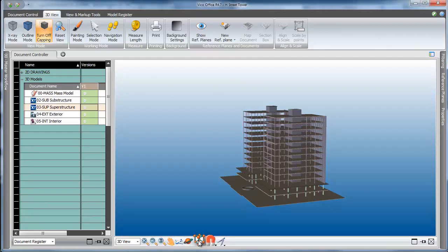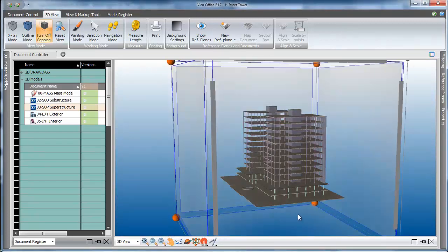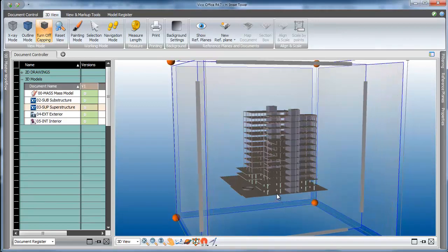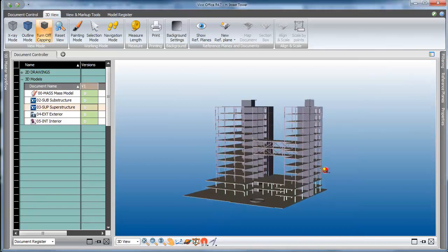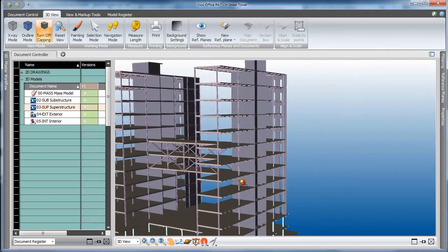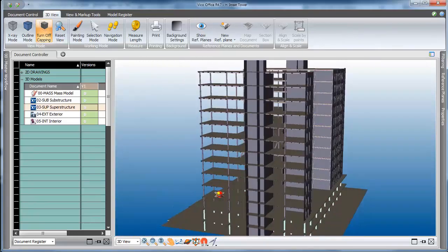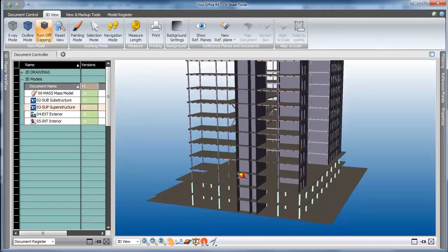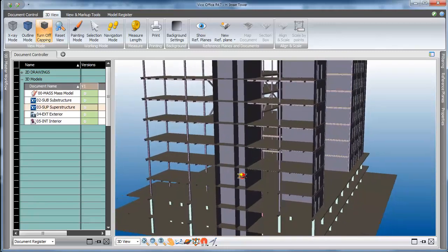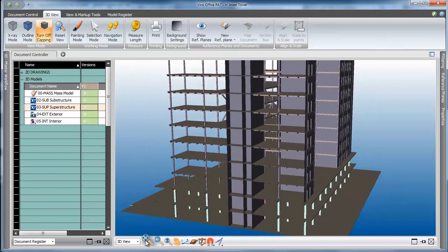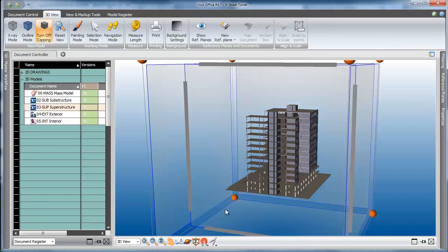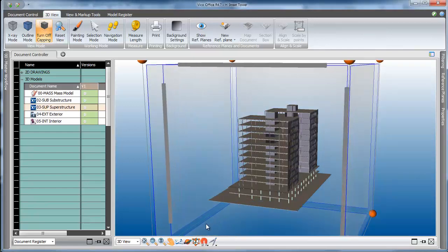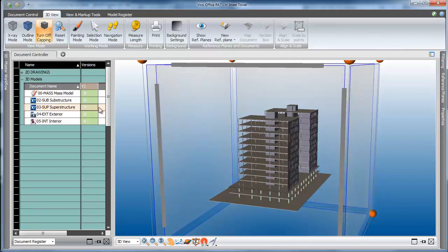If you ever want to get a better look at the model, you may want to cut a section. To do that, click on the Rubik's Cube looking icon and start to move around the faces of the section box to push away the geometry that you do not want. You can move all 6 faces at once to isolate just the part of the model that you want to see closely. To undo the sections, click Zoom Extent, choose the section icon again, and then with the pointer tool, pull the faces back out to their original position.